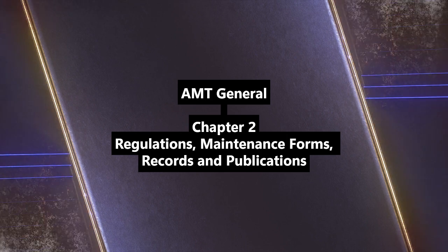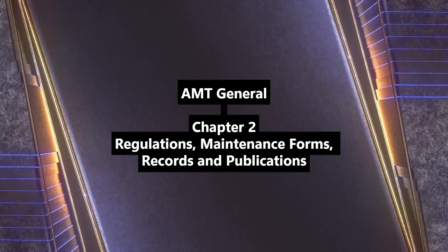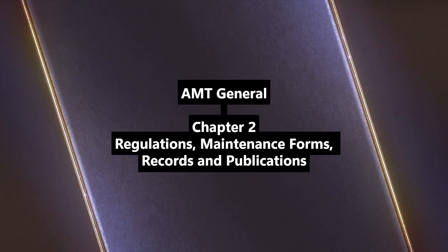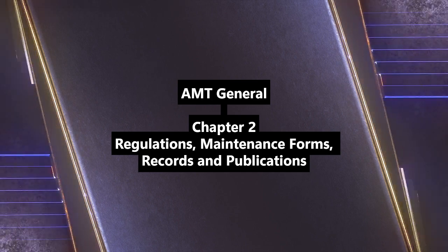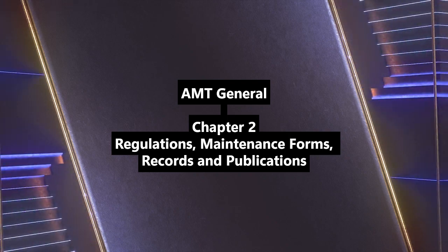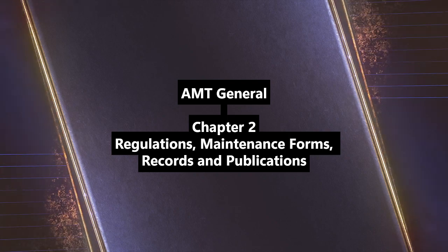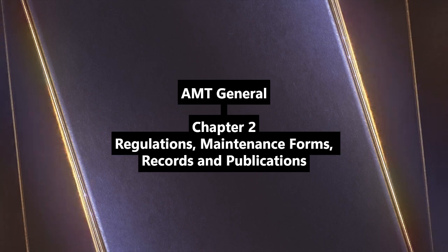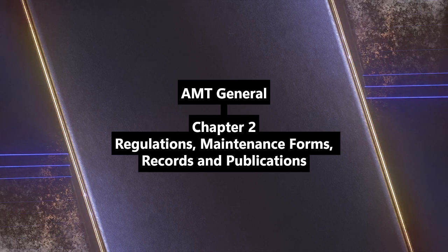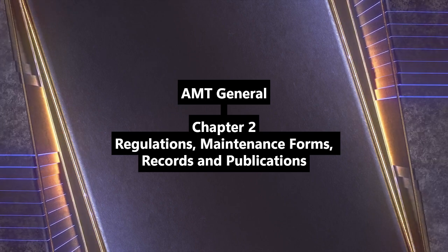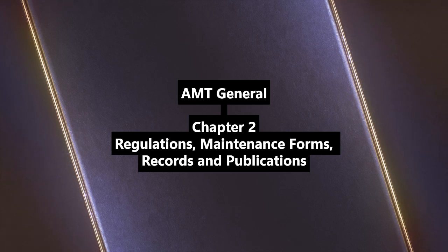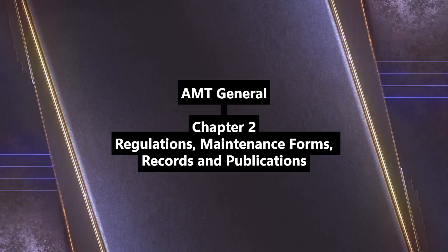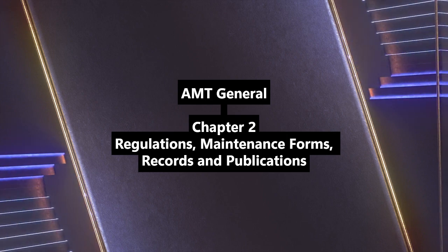Okay. What about the schools that train mechanics? That's 14 CFR Part 147 Aviation Maintenance Technician Schools. It sets the requirements for schools wanting FAA certification for airframe, powerplant, or combined AMP training. Minimum hours. 1,150 hours for A or P individually, 1,900 for combined AMP because of overlap in general subjects. The appendices detail the curriculum.